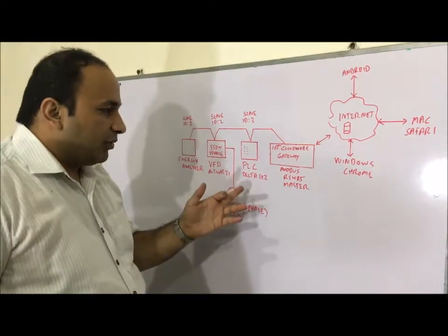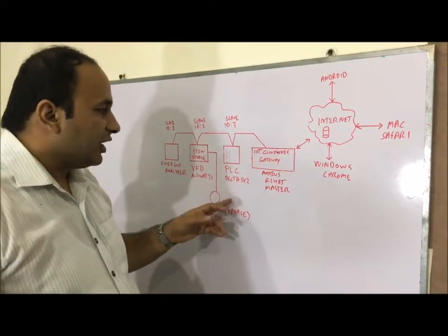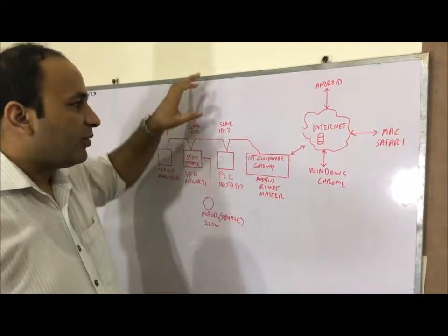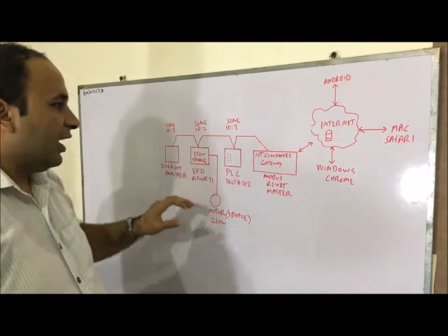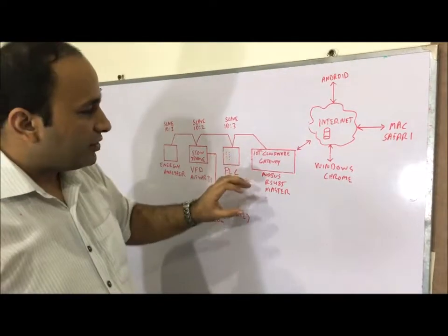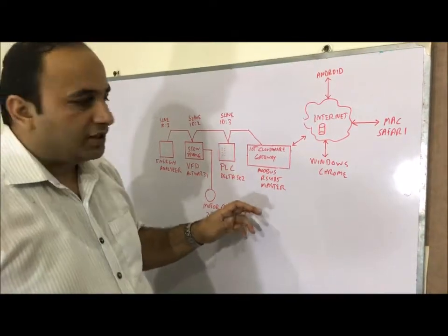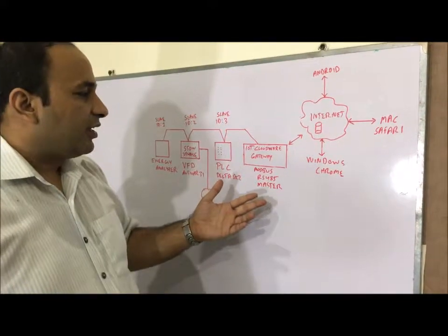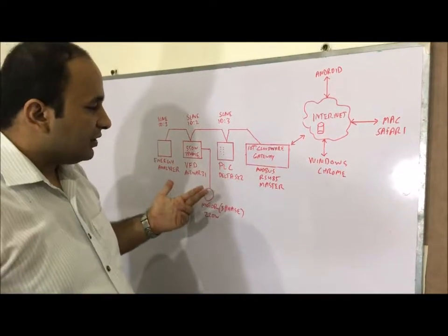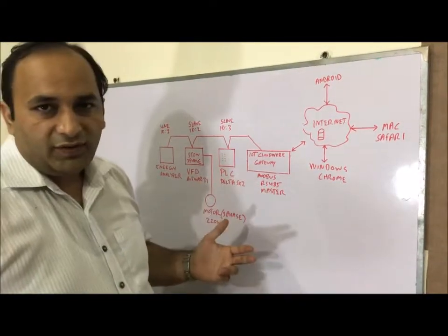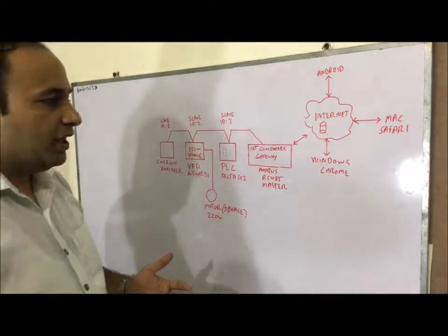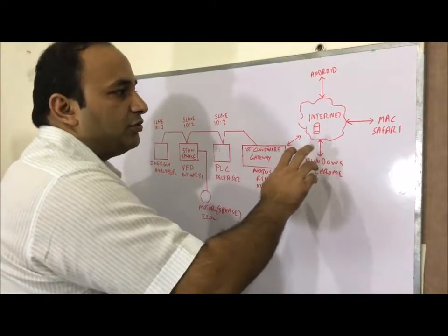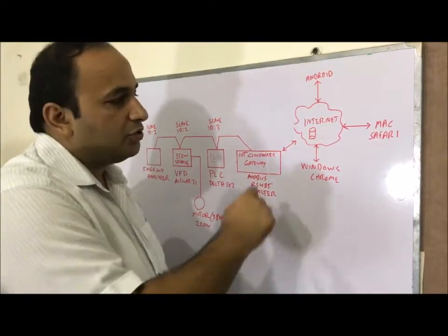Then we have another PLC down the line on the daisy chain network, which is a Delta DVP SX2. The Modbus slave ID is 3. And then ultimately the last point for this daisy chain network would be our IoT Cloudware gateway, which will be getting data from all these 3 different systems over RS485 in real time. Then this IoT Cloudware gateway is sending data across the internet in real time to our IoT Cloudware